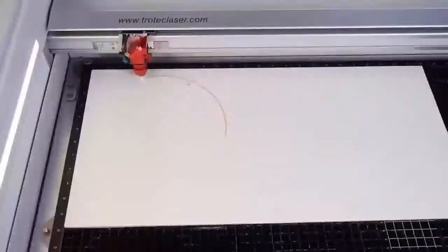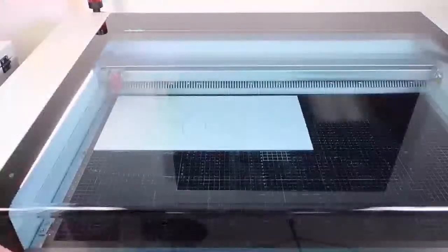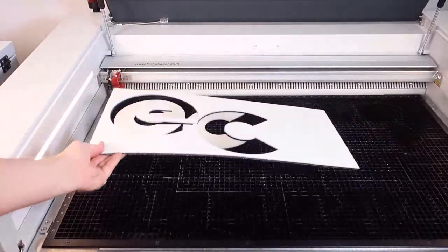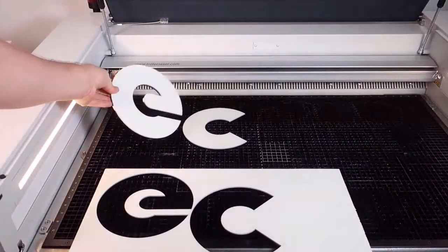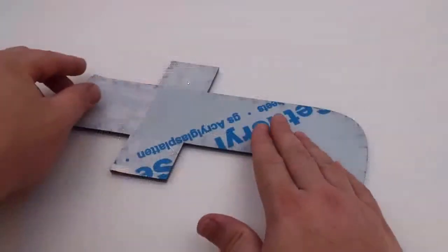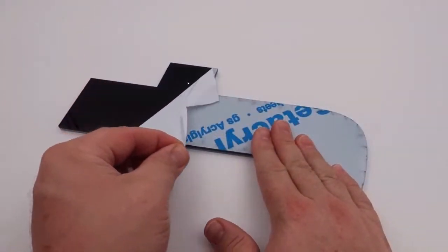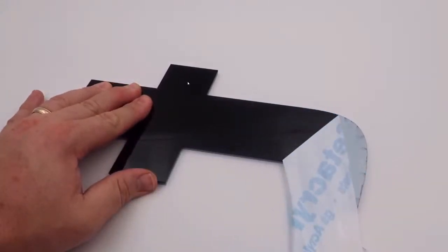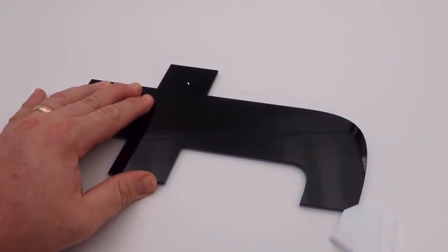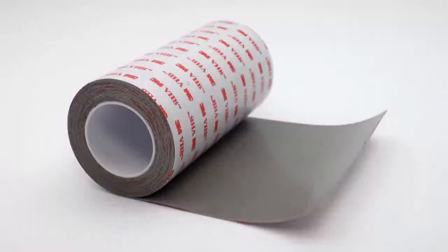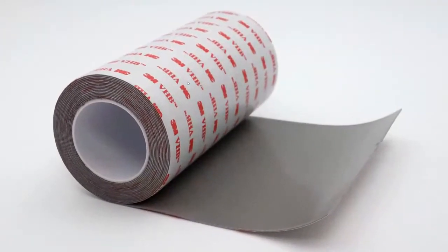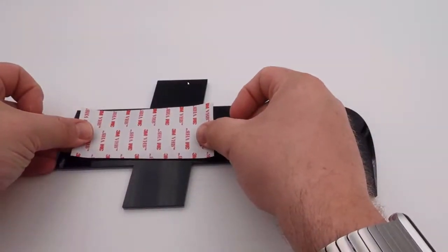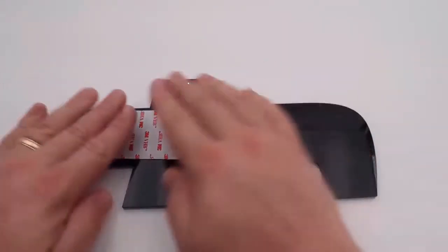material. So I'm cutting out the Trotec logo here out of a laminated white surface, black background onto the plastic itself. So this is acrylic, 2 layers cut together, and this is the back side here. So you can see the black. Now, after the letters are cut out, in this case for a dimensional sign, we're going to add a VHB double-sided adhesive. You want to use the real high quality stuff here, otherwise letters will start falling off the walls. Trust me, I've done that before.